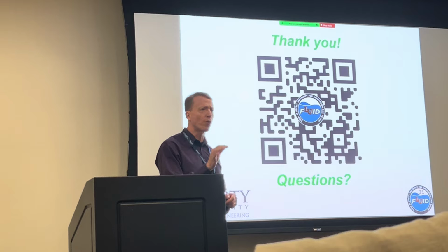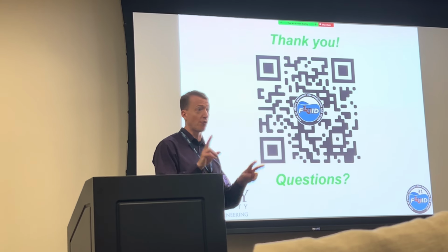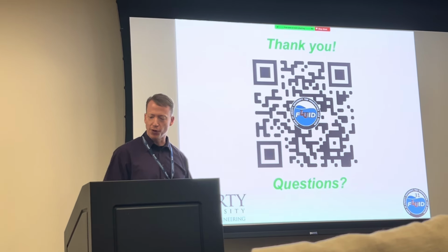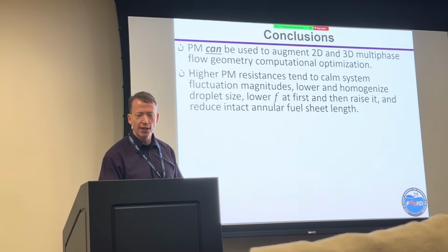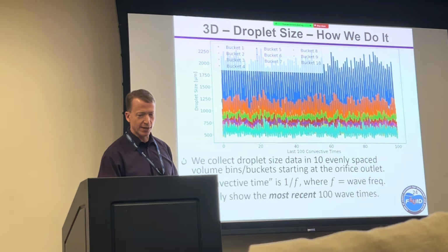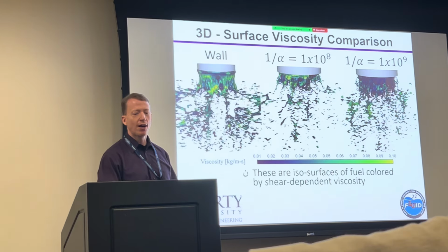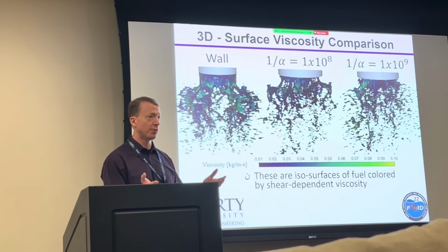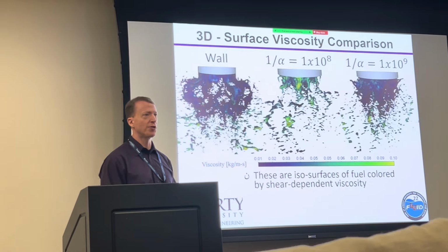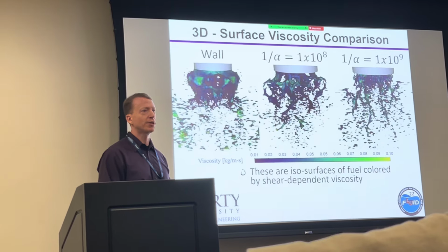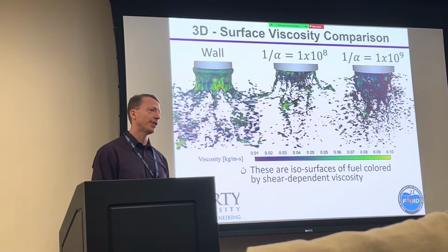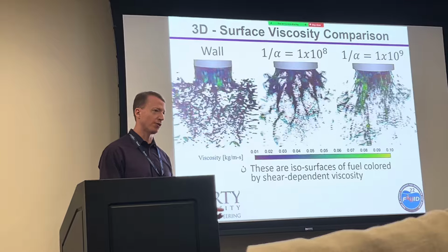We're trying to get 4 or 5 mesh elements across a given droplet. If you look at the animations, there's nothing spherical about these results. You want to call those droplets, but they're not spherical, but there's no need to remesh because we're resolving the droplet. That's why this takes months on hundreds of cores to run.